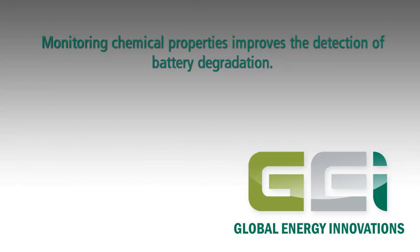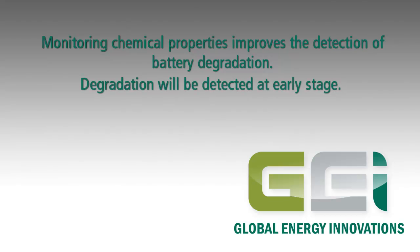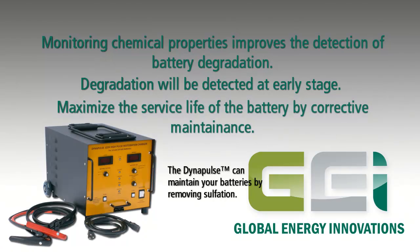Because cell scan deals with the battery chemistry, it is a better indicator than impedance for assessing battery degradation. Thanks to cell scan, you will be able to detect if batteries are in an early stage of degradation. By implementing preventative maintenance, you will be able to maintain your batteries and maximize their service life.